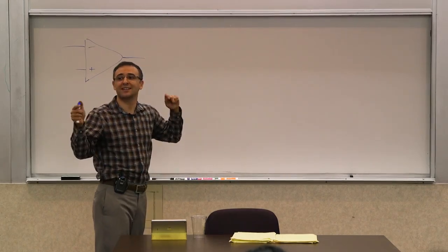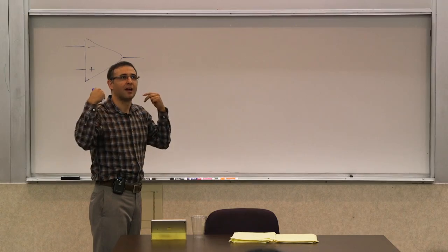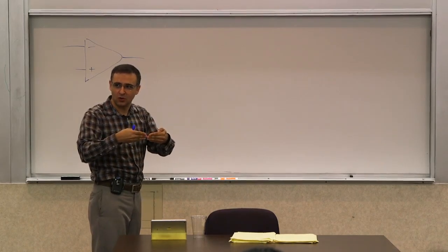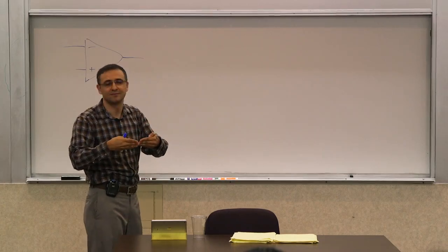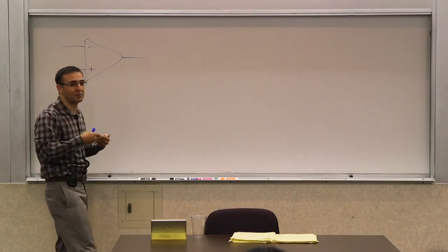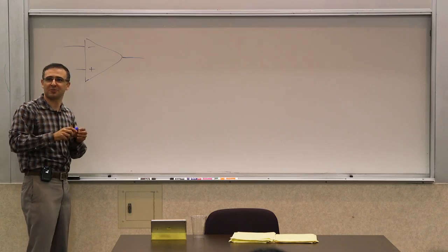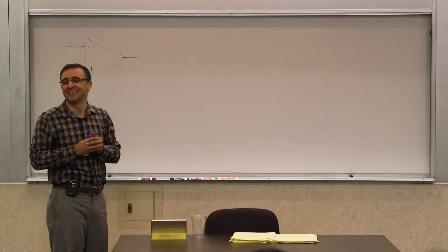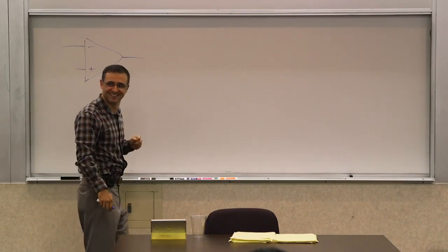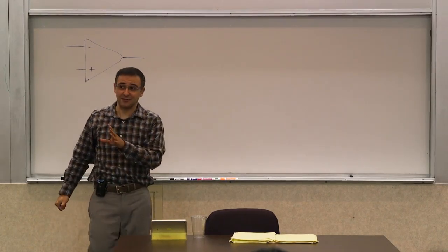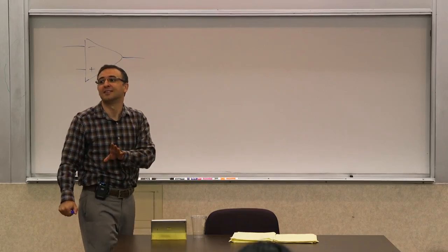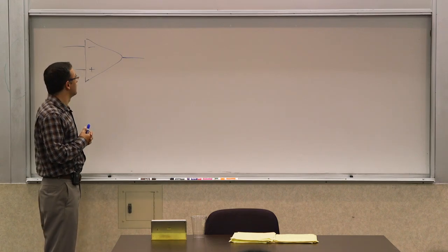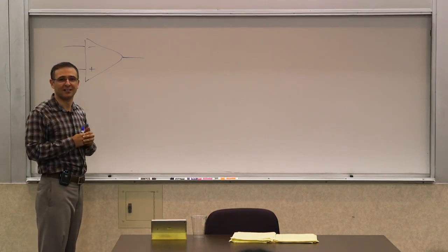When you say put 2 together, again, I want you to start practicing a more precise language. Put 2 of them in cascade, or back to back, or in series. Minus times minus is plus. That works, but you use 2 op amps and 4 resistors that way. So what if you had only 1 op amp to use? That's a reasonable thing to ask, by the way, because then you will dissipate twice as much power. And power is important because your battery will not last forever. So if I wanted to make it with 1 op amp, how would you do that?